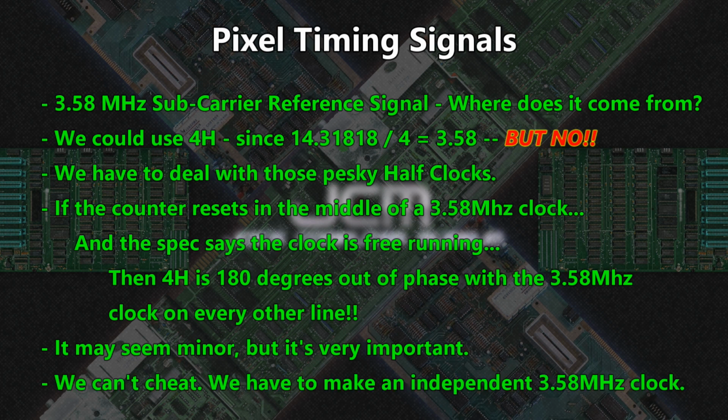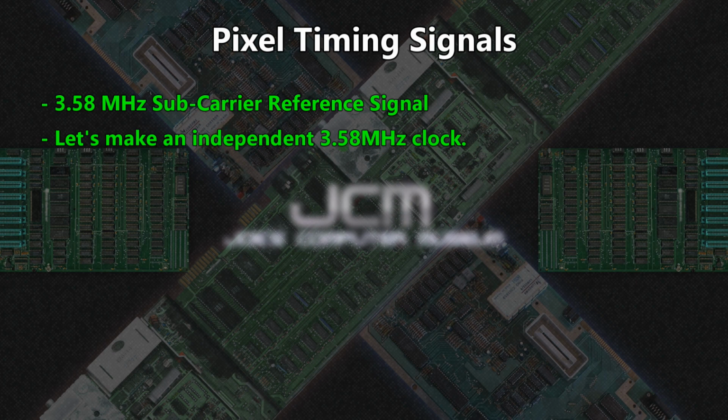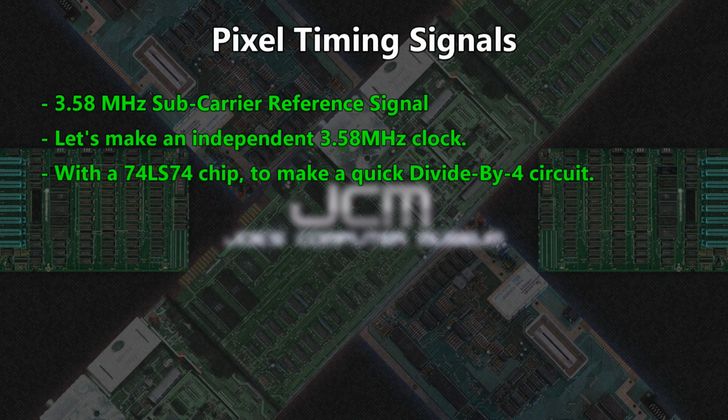Therefore, we have to make a free-running 3.58 MHz clock. We do this by using a 74LS74 as a crude counter to divide the master 14 MHz clock by 4. You can really use any kind of divider you like. I'm using this because it's cheap and because it's good to practice using the same chip in different scenarios.